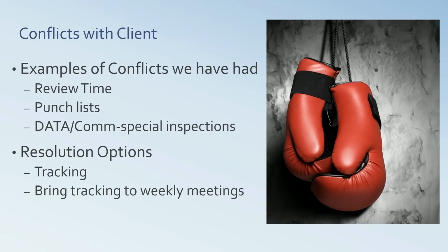Yeah, you really want to manage 3 different lists, right? You're going to have a red zone list for those doing core federal work. So that's going to be a list of deliverables, and that's going to be something that you take to weekly meetings. You're going to have your commissioning punch list, right? That's being managed between you and your commissioning agent. And then you really want one punch list, one site punch list. And it's going to be a living beast, right?